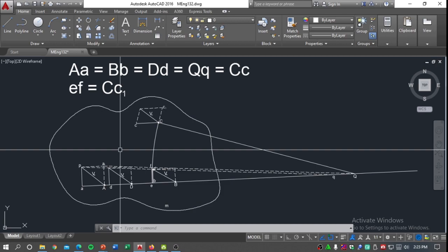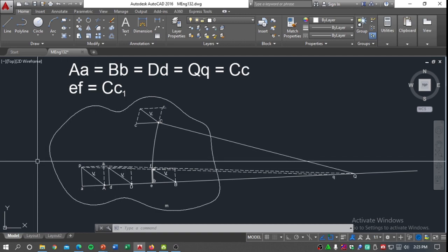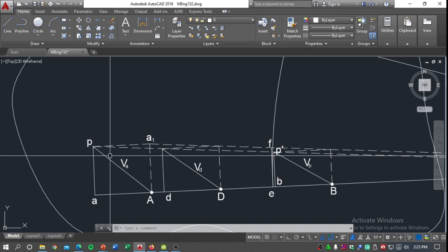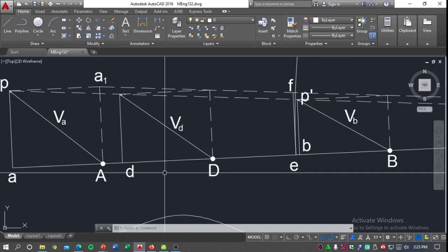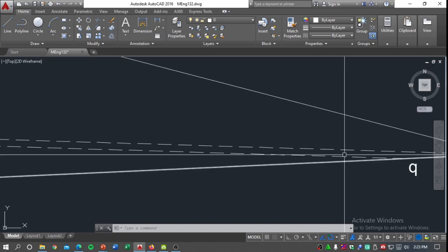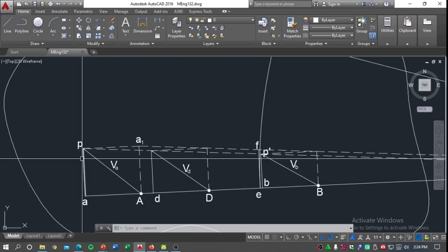Velocity vector for C involved getting first the axis Q. At first we didn't know where the axis Q was. So in order to get that, we first extended the line P prime until it intersects with the line AB, and thus we obtained point small q.